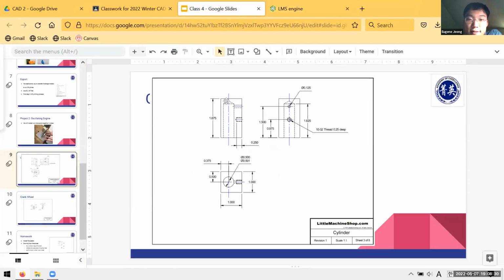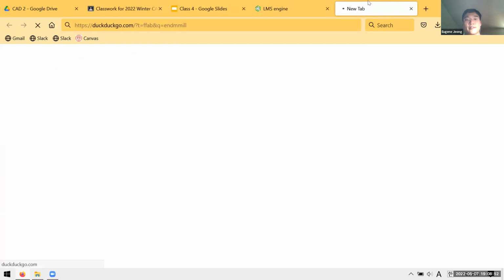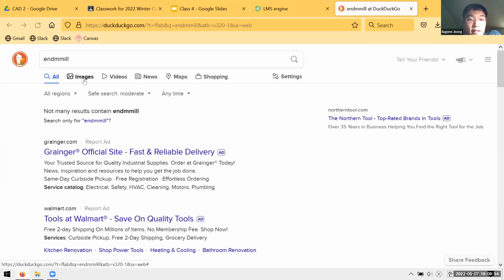All right, so anyway, these pointed tips that you see in any blind holes are basically understood to be communicating that you can use a drill bit to create this hole. It doesn't need to be flat on the bottom. Because in real life, whenever you try to create a hole that's flat on the bottom, it usually requires a bit more work. You have to use something called an end mill instead of a drill.